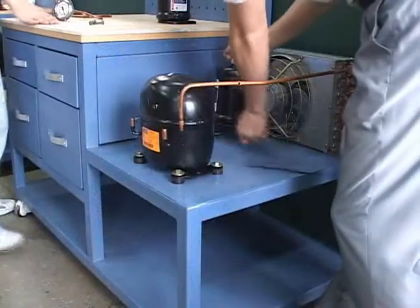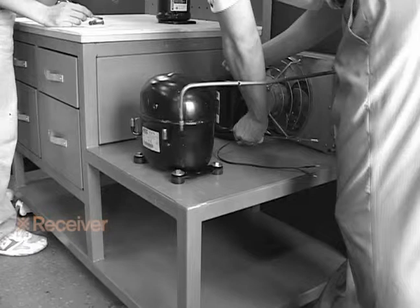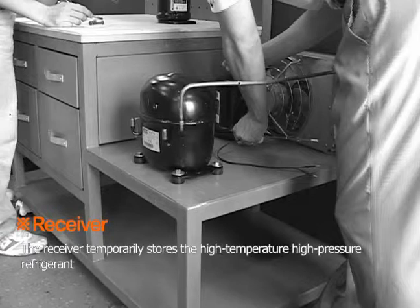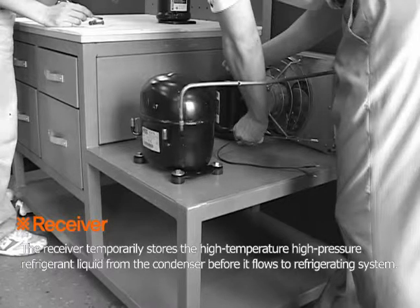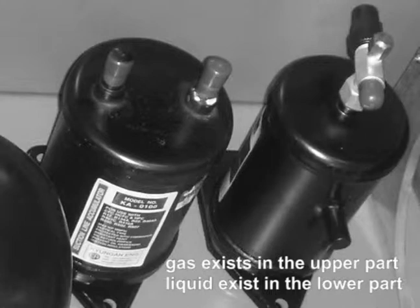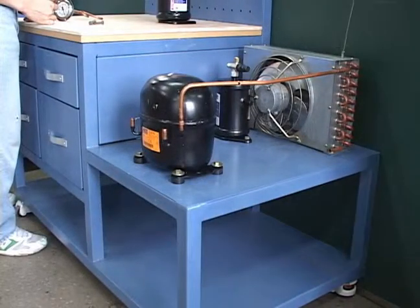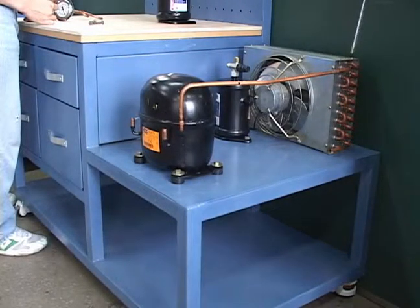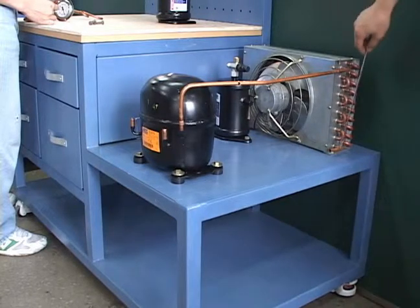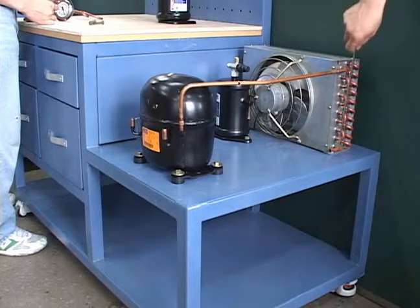Next, the receiver will be fixed on the table aligned to the bolt hole. The receiver temporarily stores the high-temperature, high-pressure refrigerant liquid from the condenser before it flows to the refrigerating system. In order to have pure liquid flow to the refrigerating system, the gas exists in the upper part and the liquid exists in the lower part. The important role of the receiver is that it stores all refrigerant when the refrigerating system has been stopped. It keeps the refrigerant during refrigerating device disassembly or operation suspension for a long time.